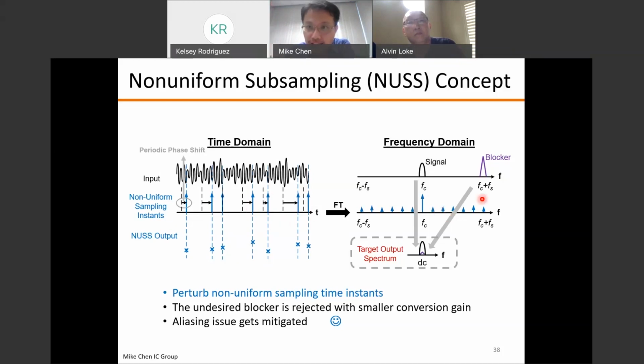So what you can do is start with some desired profile, and then look at that FFT relationship. You can hand calculate what the shape is, but it probably cannot get exactly what you wanted. So then what we did is we actually run iterative algorithms, like gradient descent. We start from those hand-calculated time points, and we start to perturb and adapt, saying, hey, for example, I really want to knock down this energy at these particular frequencies.